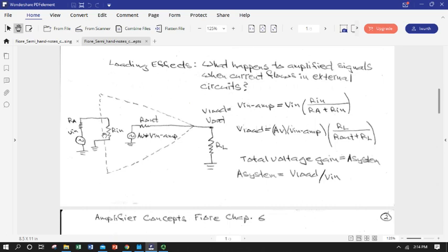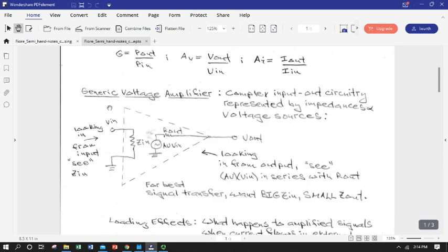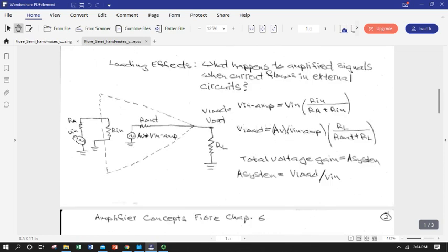So instead of just putting in an ideal voltage input to our amplifier, we're going to have a real live voltage source, like maybe the arbitrary waveform generator of our PicoScope or other function generator, and it's going to have its own series resistance. So we'll set our input signal here, and then we're going to drop some voltage over the output resistance of that source itself before we ever get into the amplifier.